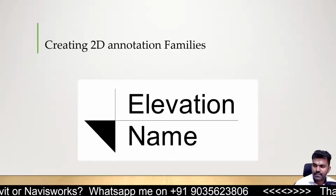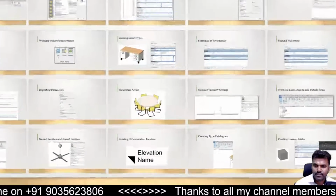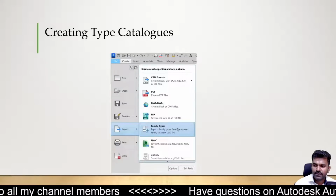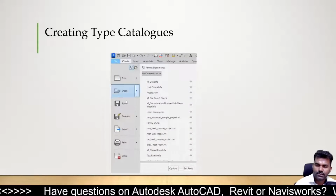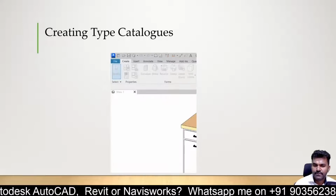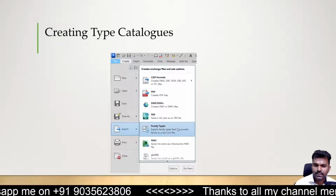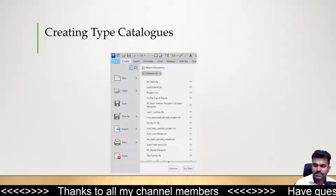Okay, let's go to the next one. Type catalogs. It's an advanced topic. Not everybody will do type catalogs. Once you learn all the other topics, then you can come to type catalogs. A type catalog will help you in reducing the family size in your project, and it's also easy to update the types in an Excel sheet.